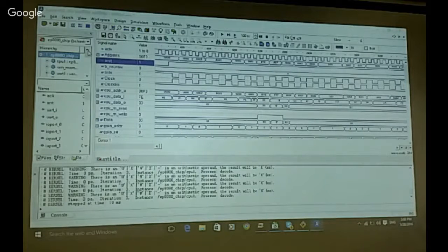If you click there, this name panel shows all the signals in this component. And these are things like clock and clear. These are the same signals from the top level module. The address, we have seen here. But if you go down here, you can see all the names of all the internal registers and internal signals. And you can drag these signals into the panel, and then the simulator will show you the internal signals.